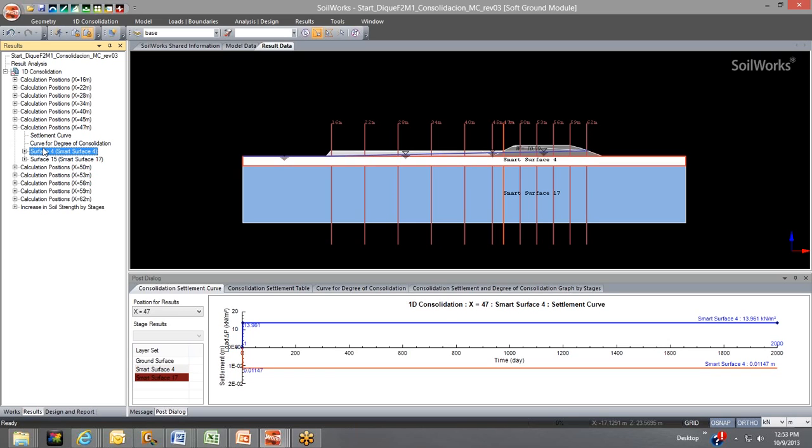And I'm just double checking to see if there's any changes, but it appears that all the settlement in this particular project is sort of immediate. So after immediate settlement, what the program is telling you is that there won't be any other settlement afterwards. So even a couple of years after the immediate settlement, if none of these conditions change, then the settlement or the displacement will be the same.